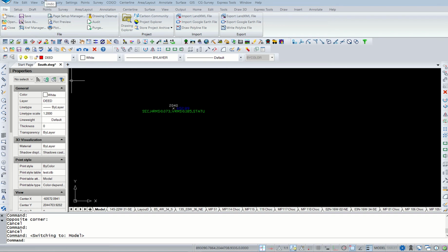So here's my section corner, and we measured to the references, which were 4 trees, using a tape and compass, because we could not get direct measurement on it with GPS. So I will have to key in those angles and distances. I'm looking at the field book now. You can't see the field book, but we've got 4 pine trees here, so let me get started.